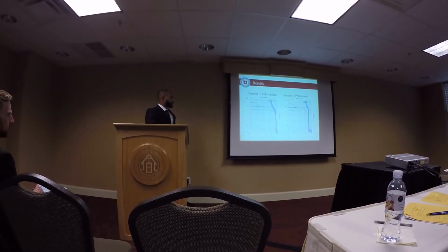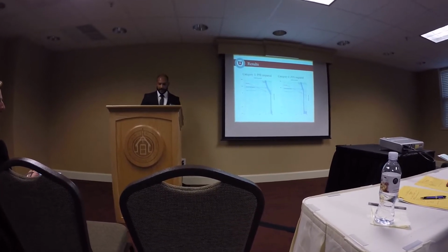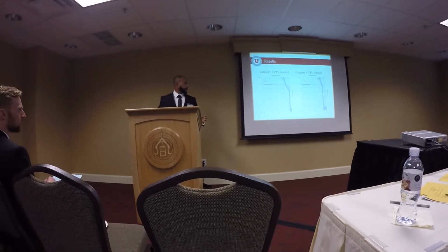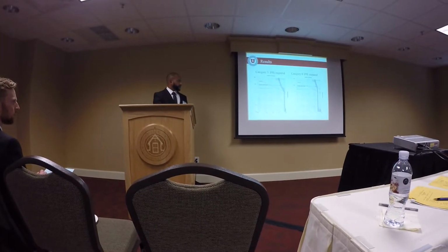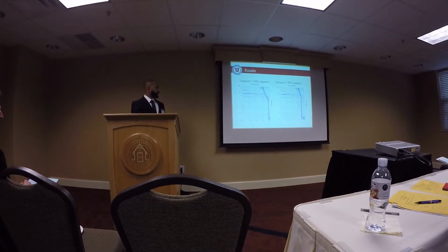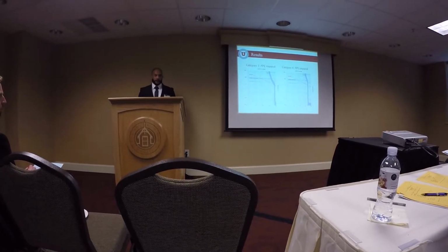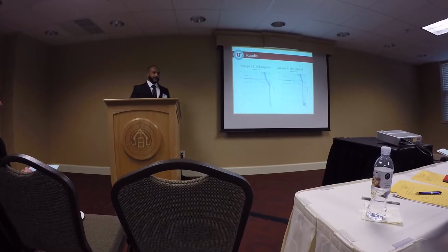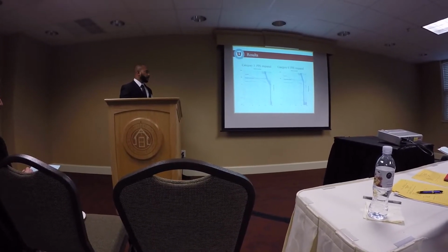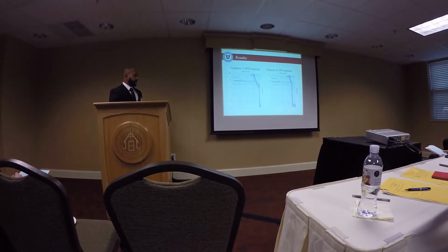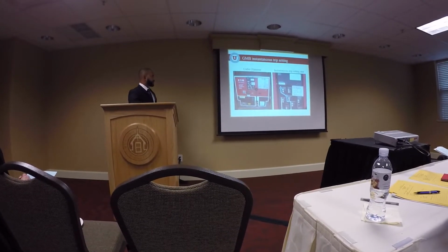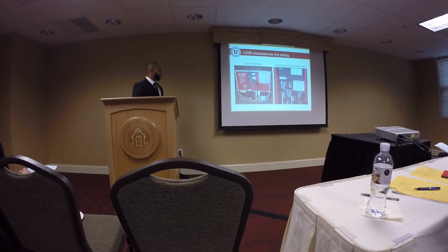After finding the short-time delays and short-time pickup time, I was able to reduce most of them from Category 3 to Category 0 PPE. Does this mean that anytime the generator kicks in, the breaker is going to activate and shut off the power system? No. The newer types of breakers are extremely smart. This is an example of a Cutler-Hammer generator main breaker that we use.